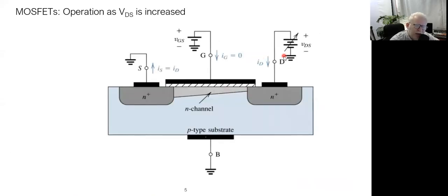That's why we add this VD, or the drain voltage. The drain voltage will act to attract electrons from the source. So these electrons will start to move through the channel to reach the drain, and then you have electrons moving, and then you have a current. This is simply how the MOSFET works. Whenever you increase this VD, that simply means that you increase the attraction force. So more and more electrons are going to move from the source to the drain. That's why you have a higher current. So in a very simple manner, the higher the VD, the higher the ID.